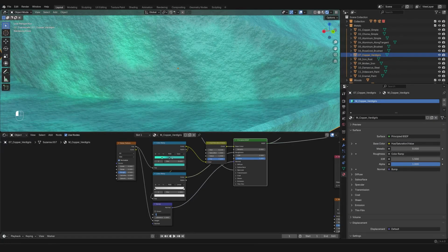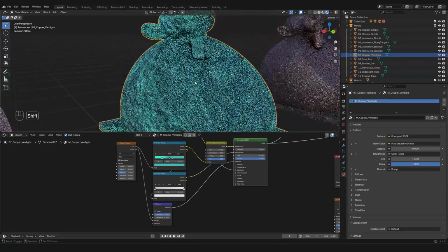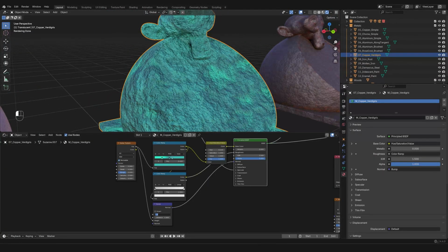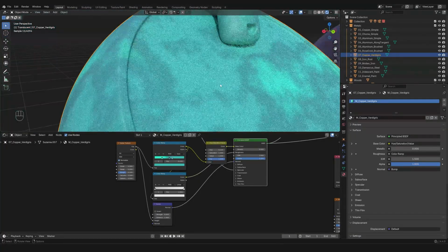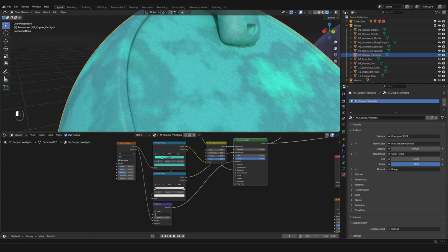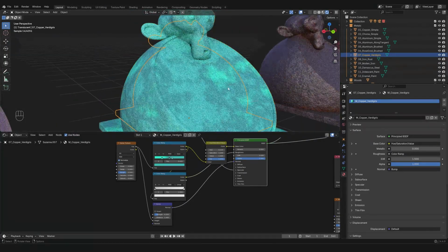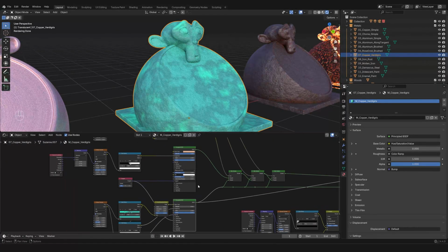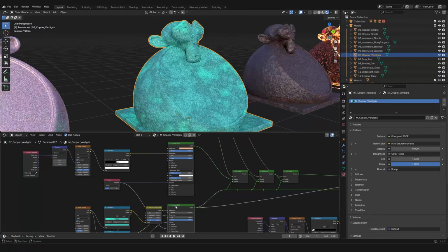And if I turn this up, I can control it and bring it to an extreme, of course. And if this was 0, we would not have any effect at all. And so I'm going to leave it to a 0.25, which works for me. This feels right. And so to recap, what do we have here? We have this metal and this, which represent the verdigris. This is a patina. This is when metal oxidates over time.